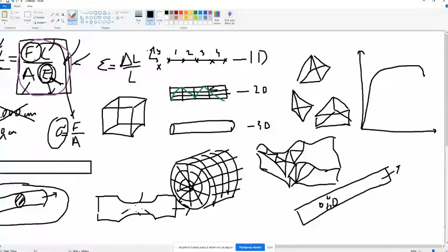We know the area, or the system is able to read the data, or with the help of a camera, it can understand the area of the sample. But generally, you are entering the cross-sectional area data, and up to the result of the load cell, your force will be there, the area measured, and the computer, the tensile test setup, is going to give you the stress value.